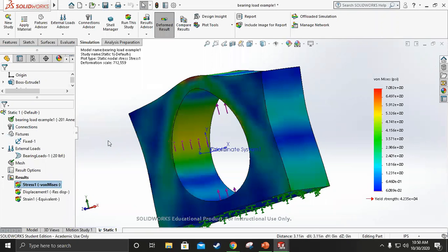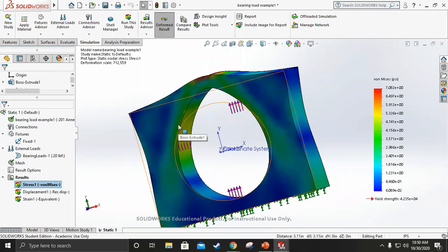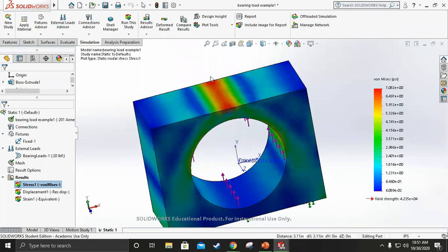As you can see, it's to be expected that you're pulling the rod that's inside the bearing upwards with the belt, so it would cause a deformation like that. Of course, you could also do it in the X direction. You could do it in the Y direction as well, and even kind of in the Z direction, because there's no wall in between, so it only gives you two at a time. And as you can see, most of the stress is right here because that's the center of where the pole or the tube that's being pulled is at.